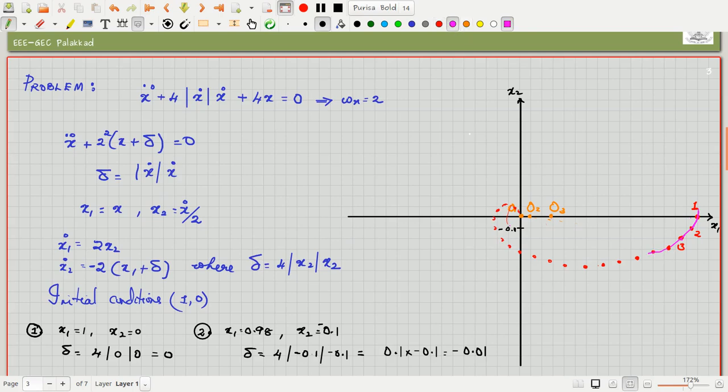It is in fact short arcs; we are drawing the short arcs to find the new points. This is how we move forward using the delta method, and we come to the equilibrium point. So these O1, O2, O3 will be shifting, O4, O5, like that.